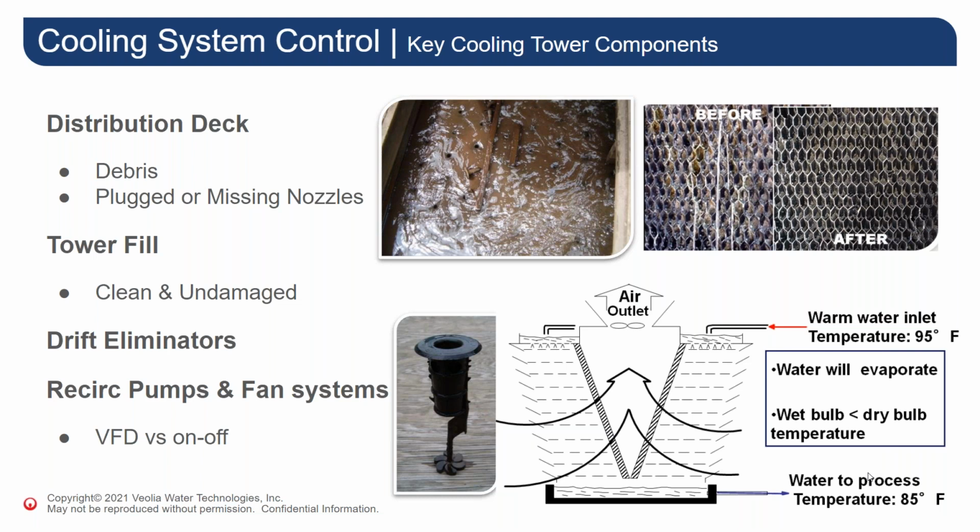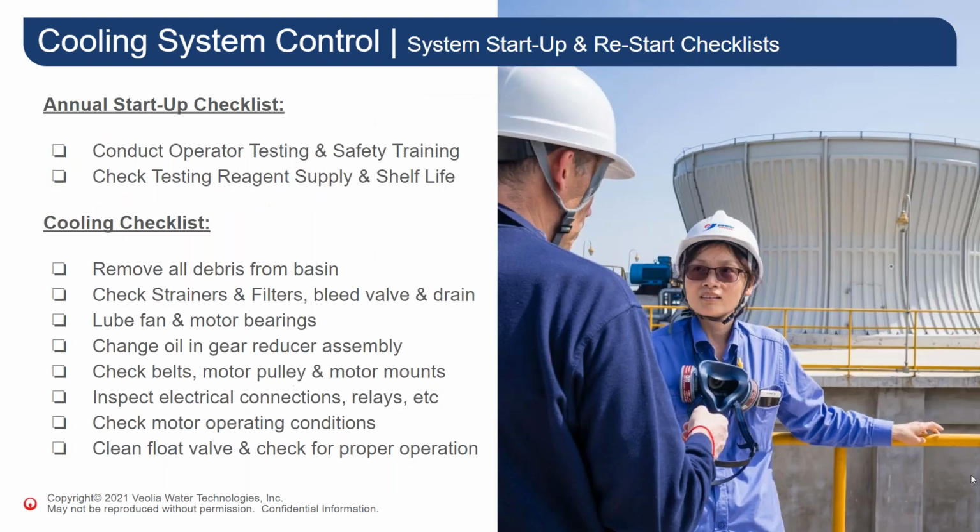The cooling tower fans must be maintained and operating correctly in order for the airflow to water ratio to be maintained. The fans can be gear driven or belt driven and consume a good portion of the electricity used by the cooling system.